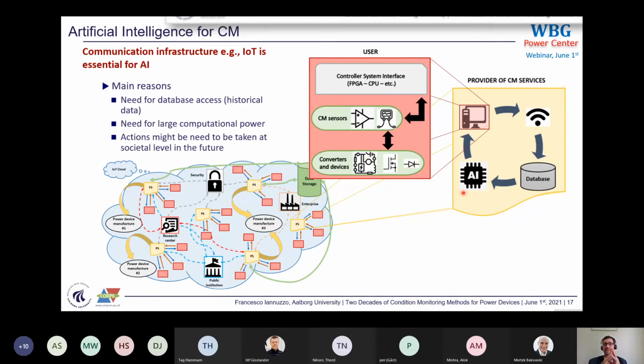I know for certain they are very active on capacitors, and they can detect, for example, drift in time of ESR, equivalent series resistance, and also loss of capacitance over time, because basically in the intrinsic structure of your capacitor, you have a lot of plates which are in parallel or just wound together, and then the side contacts get degraded over time, and then the overall capacitance decreases. So the answer is yes, there is a lot which is done there, and yes, it is a lack of information here. Sorry about this.